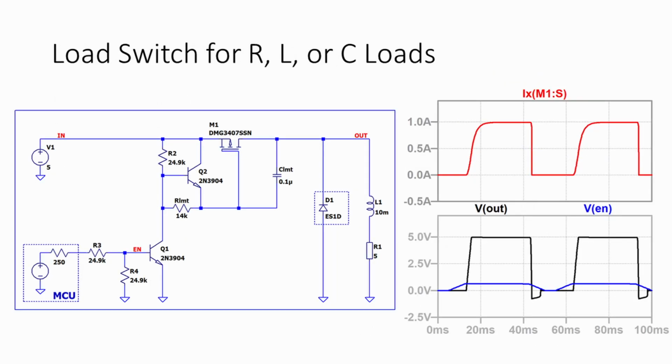So here's the final look at the load switch design that can safely handle both inductive and capacitive loads. The waveforms for drain voltage and FET current are shown. The waveforms show that the voltage is slow to rise for the inductive load, since we're limiting the ramp rate using the C-limit charging approach. There are situations where the inductive load requires a fast dV/dt transition to turn on, and keeping the capacitive load protection in place doesn't work well with that.